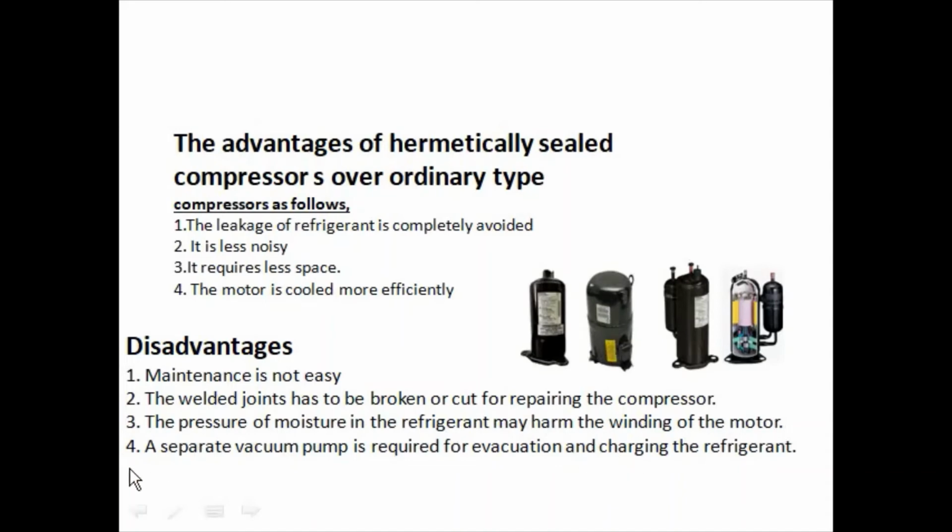Point 4, a separate vacuum pump is required for evacuation and charging the refrigerant. As we have seen in the previous videos, before performing charging, you have to start from point 1, which is evacuation. Also when working with a refrigerator with this hermetically sealed compressor, before starting charging, you have to start with evacuation.